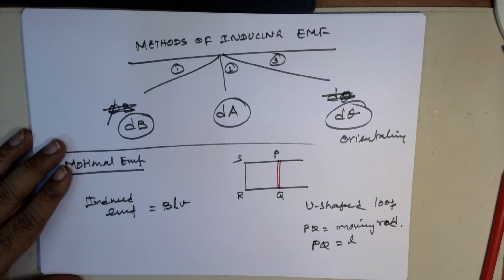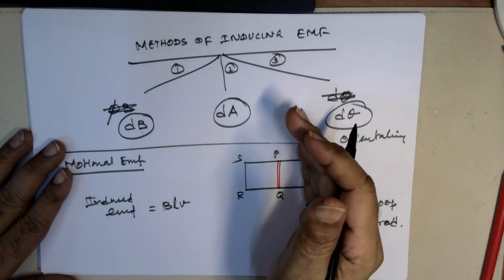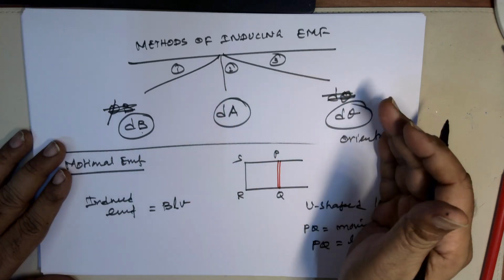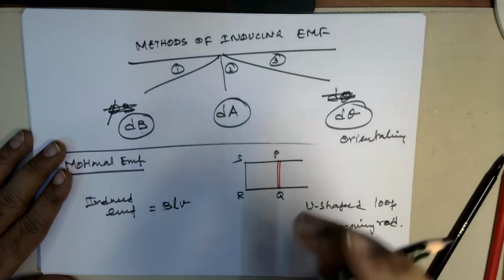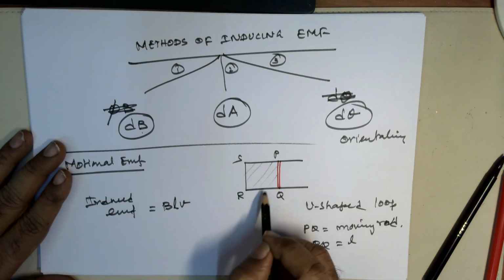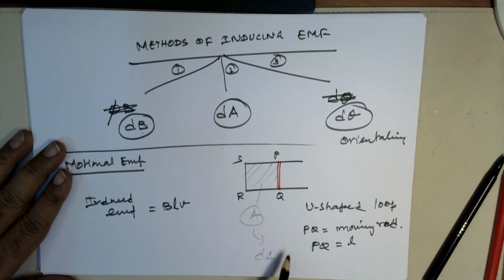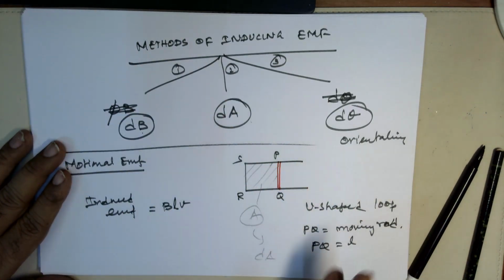Okay. So when the area of the coil through which the magnetic field is passing is changed by moving the rod into or out of the loop, so this side or this side, this area can be altered. Are you able to follow? So this is the area enveloped by the coil, A, and this can be altered as dA. By changing this, you get how fast it is getting changed. So that is also very important.